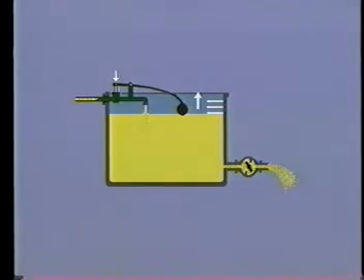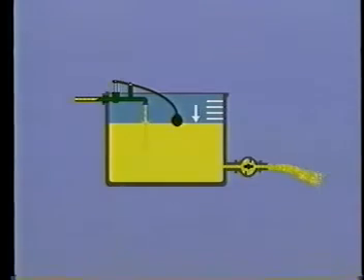But look what happens when someone opens the outflow tap so water leaves the tank in greater volume, representing a large load change. The water level drops by a large amount, causing the inflow valve to open wider. The valve will have to open wide enough so that the new inflow of water equals the new outflow. Once this occurs, the water level will stay constant. But in order for the inflow valve to be opened wide enough, the float must be lower in the tank.